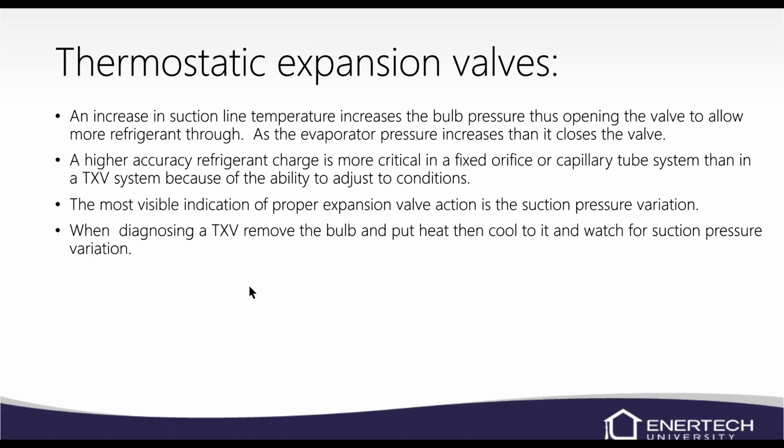When you're in first stage on a compressor, you're going to be running higher pressures than in second stage, just as a side note. So I would recommend putting it in second stage when you're doing these checks, and then look for your suction pressure variation. Superheat and subcooling will tell you as well, and we'll get into that in just a second.